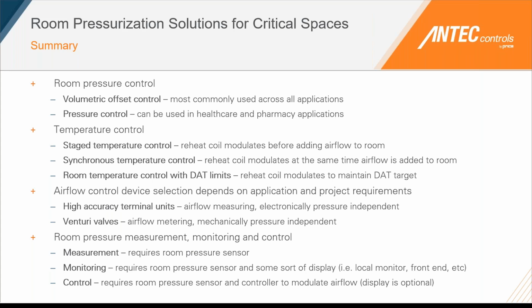Additionally, we talked about the airflow control devices, which may depend on the application and project requirements. With a high accuracy terminal unit, we're directly measuring the airflow, and that's an electronically pressure independent valve. And then we have venturi valves, which are metering the airflow and are mechanically pressure independent.